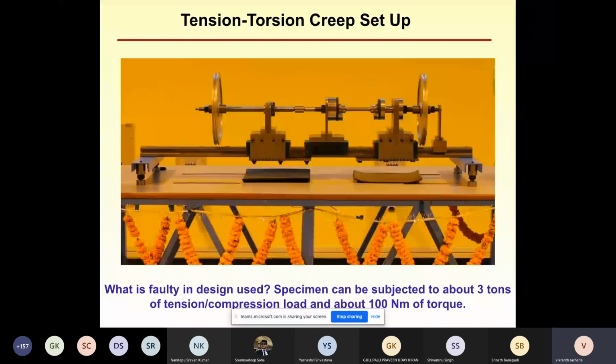It will be pi multiplied by 300 divided by 5. So you get a huge mechanical advantage in this particular system. By applying a weight of 1 kg, how much force can you generate on this particular specimen in this arrangement? Neglect losses.